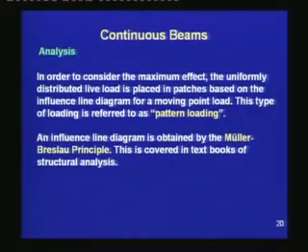This type of patch loading is termed as pattern loading. Thus, the live load in a building or in a bridge is not just placed uniformly, it is also placed in patches, and this type of loading is called pattern loading. An influence line diagram is obtained by the Muller-Breslau principle. This is covered in textbooks of structural analysis.